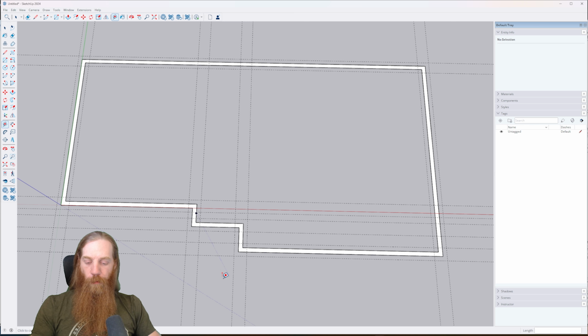So before we do the footing, I want to finish off this foundation wall, just getting the bulk of it into the model, right? So we're going to press P. P is the push-pull mode, which is right here on the sidebar. What you do with that, once you select an object, well, we've created a two-dimensional object, right? At this time, we need to make this three-dimensional. We need to pull that wall all the way up to the height that we want. So we just put the cursor on it with our push-pull selected. You know it's on there because the whole thing gets shaded a little bit blue.